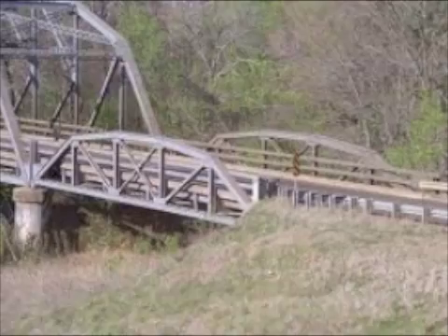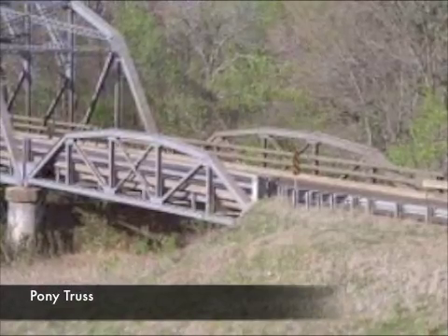There are three types of roadways that a bridge can have. The first is a deck truss. This is a type of bridge on which the road deck lies above the structural parts. The supporting beams of the truss structure are arranged in triangular patterns to distribute loads and ensure the bridge stays stable. The second type of roadway shown is a pony truss.